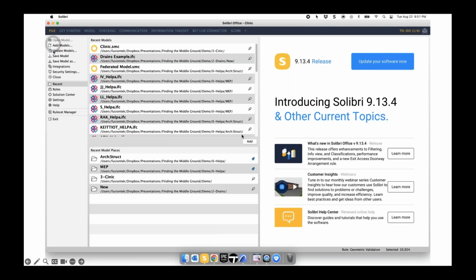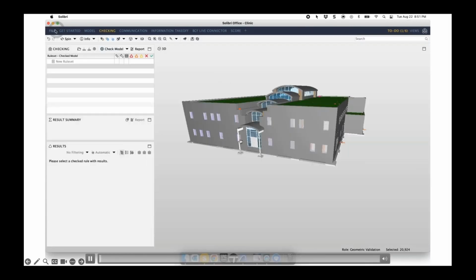So how can we get Solibri to look at every single door and make sure that every single door has a light switch within 1, 2, or 3 feet? Yes. In the next example, we're just going to go to our rule set manager. We're not going to classify any data because we can just access the data through another means. So there's flexibility in how you do this, but we're just going to go right to the rule set manager and search for that.